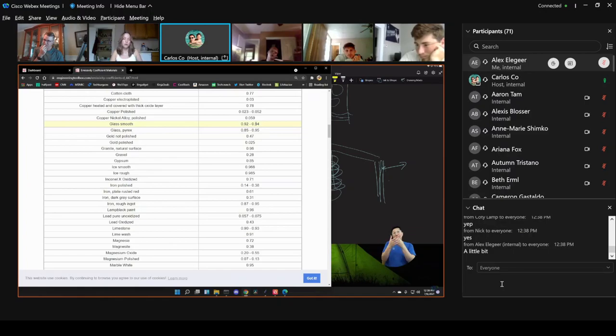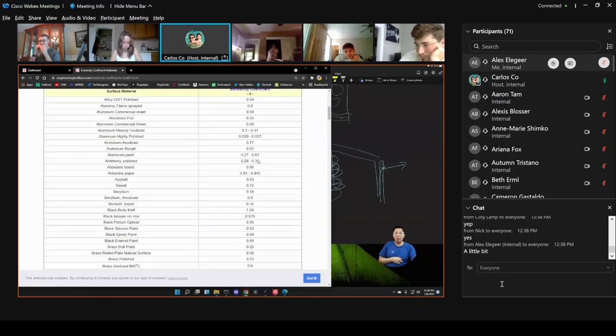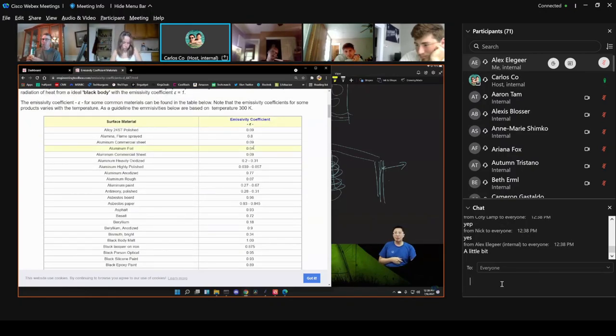So if that thing is at 400 kelvins, that's 400 to the fourth times the 5.67 times 10 to the minus 8 watts per meter squared kelvin to the fourth. You multiply that together, that's the emissivity times 0.94. But if you wrap that thing up in aluminum foil, the surface is not glass anymore. The emissivity drops all the way down to about 0.05 or so. And so you significantly decrease your heat loss by radiation. That's why you wrap it up in aluminum foil. Got that? That's the reason why: you minimize radiative heat losses. It works.